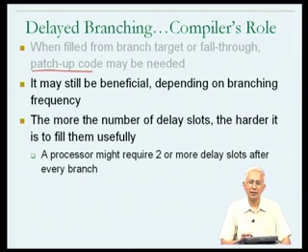In other words, after the branch, when the branch instruction is executed, it might not be the case that the condition and the target address can be resolved in the ID stage. It may be that it was not feasible to do that in a particular processor pipeline, and the result may be that there is a need for 2 or 3 or maybe even 4 branch delay slots, in which case that would be a warning to the programmer and the compiler in the instruction set architecture manual, for example, that there are 2 branch delay slots.